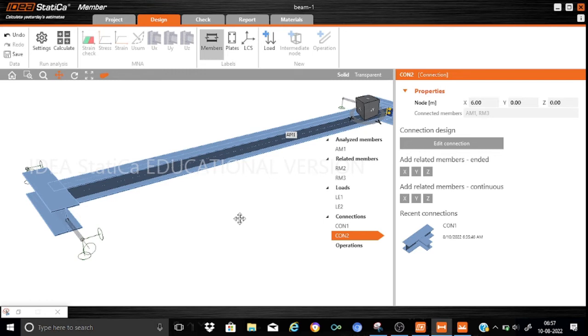I use either a plan bracing that can effectively control what we call the out-of-plane translation of the compression flange, or it can also be restrained by means of some construction. For example, suppose you have a beam that supports a corrugated RCC deck slab which is connected to the compression flange through studs. In that case also, you can assume that the beam is fully restrained, right?